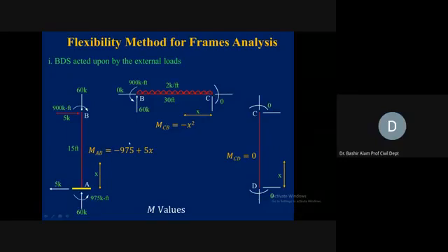So now at joint B, all the member actions are calculated. The vertical reaction is 60. Horizontal is 0, and the moment is counterclockwise 900, which is coming from 2 times 30 divided by 2. Now this whole member is in equilibrium. All the boundary conditions and everything is met.